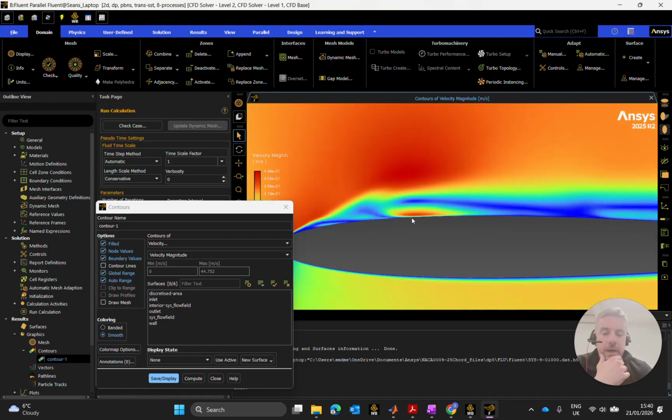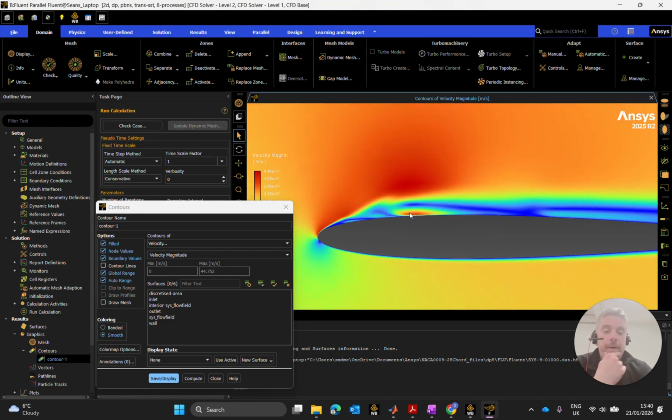And at the bigger angle of attack, this is what we're getting here. I didn't check design point 2 to retain the data when we were looking at that, but again, it depends on the time that the solver finished and was satisfied that everything was converged. But we could see, certainly at angles of attack of 3, 4, 5, and 6 degrees, definitely, laminar separation bubbles are there.